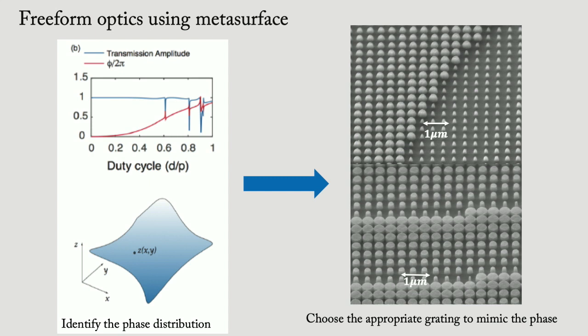It's very sensitive to fabrication. But it turns out in metasurface, even though you have a lot of scatterers, your fabrication may not be completely perfect, and it still works very well. The reason is the field is distributed over the whole metasurface. So if you have small problems in some scatterers, that doesn't really affect the overall performance, which is not the case for various nanophotonic structures, for example, waveguides or optical resonators that we all are working with, and we know that fabrication is extremely important for that.